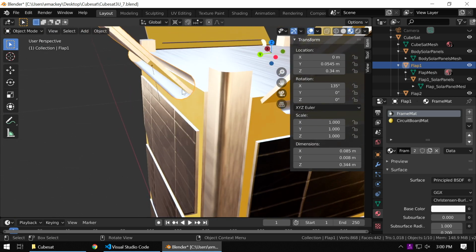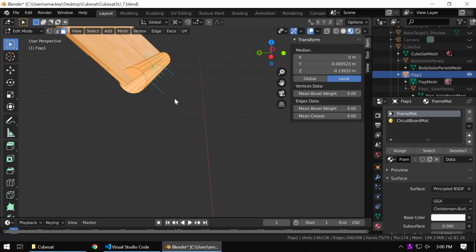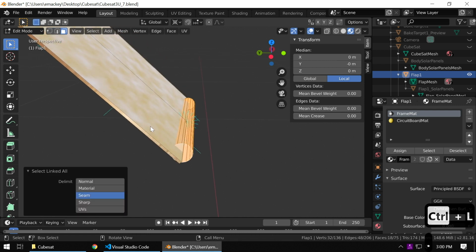So that's a problem. And for baking ambient occlusion, it's trying to figure out how much light is coming into the inside of the hinge. And the answer is none. And it colors it all black. Yeah, I mean, the surface normal is actually a crucial piece to the ambient occlusion calculation. So if it's facing the wrong way, you'll find out pretty quickly. Yes. And as it happens, when we were building this, we had the surface normal turned on.